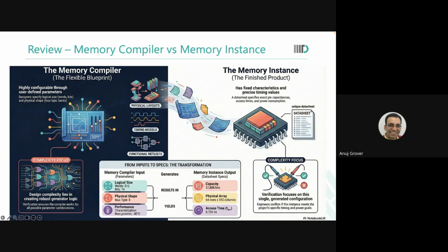So for every technology, I will define a particular standard load. For example, for an automotive technology, it will say that the standard load is 10 femtofarads. Now, even if Madhav said, no, I had seen only 5 femtofarads, Madhav also characterizes at 10. The one who had seen 20, he also characterizes at 10. The one who had seen 200, he also characterizes at 10.